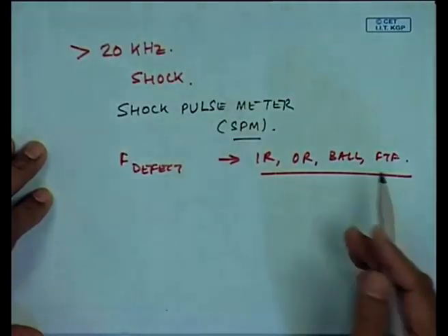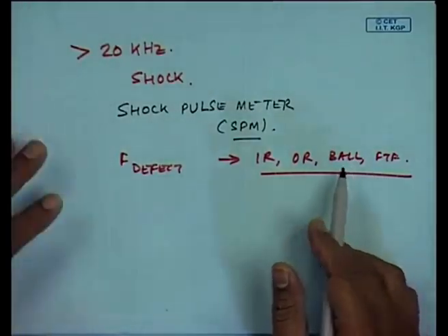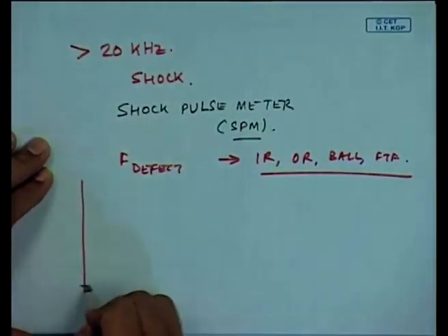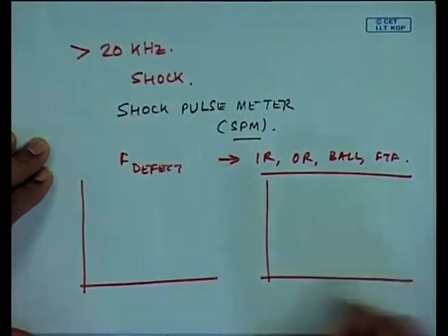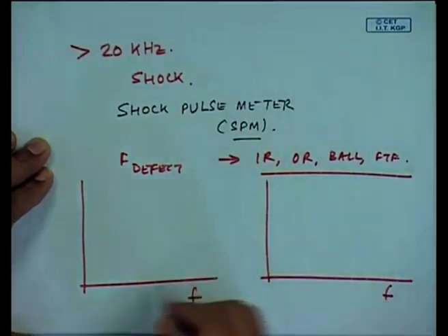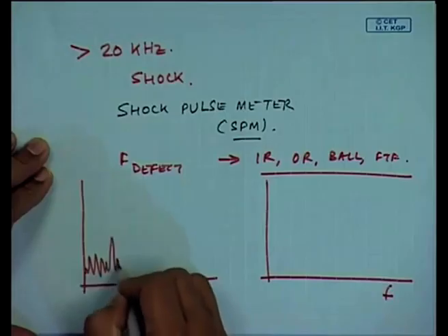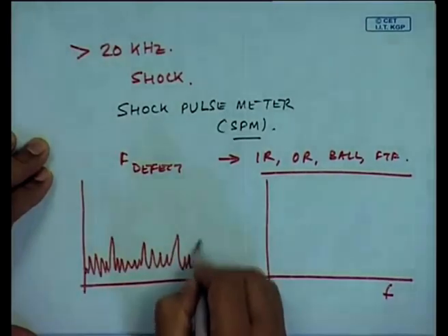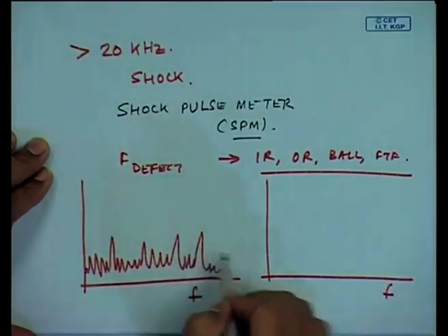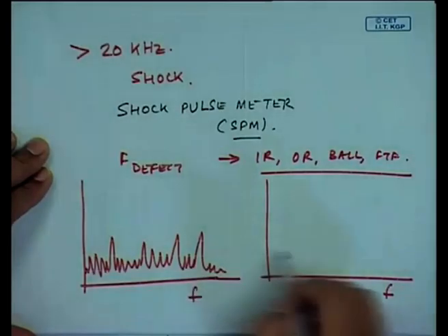Okay. And then when we talk about the fault diagnostics of bearings, I will give you certain actual measured values and measured spectrums of the inner race frequency, outer race frequency after the modulation. I will give you two frequency spectrums, one without envelope analysis, one with envelope analysis. One without envelope analysis, where this could be the defect frequencies, but if I do it with the envelope analysis,